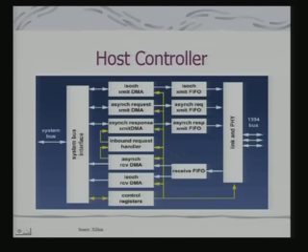Now, here obviously you will find that for different kinds of data, different DMA channels have been identified. And here you find that the inbound request handler is different from the other transmit handlers, because these DMA channels have to be configured and handled differently depending on how the data is mapped onto the memory for subsequent usage.